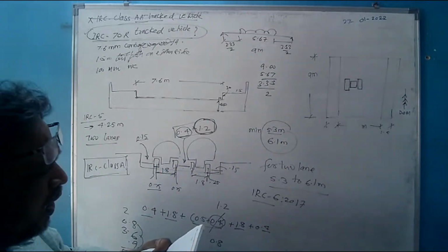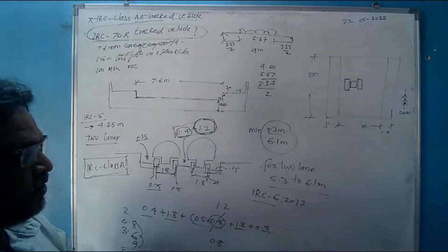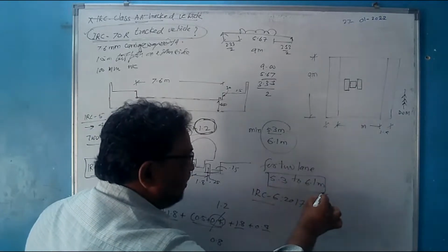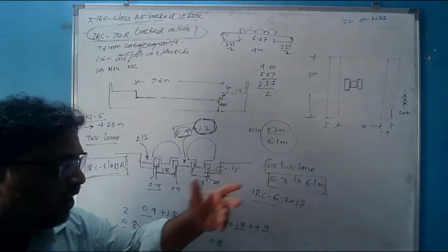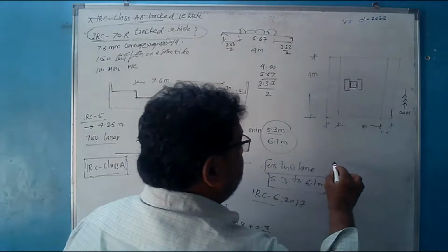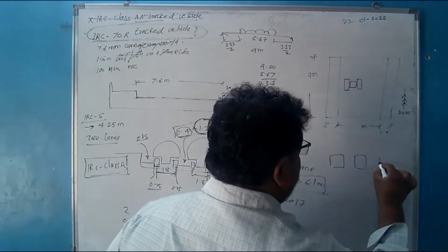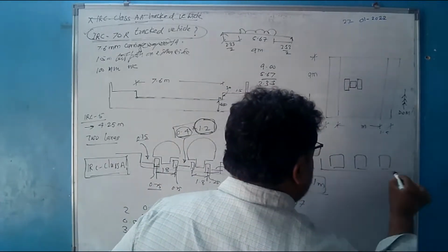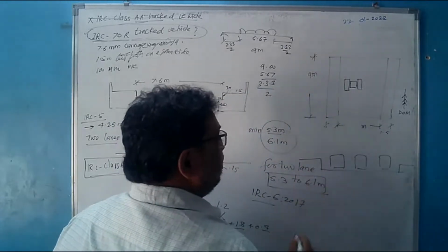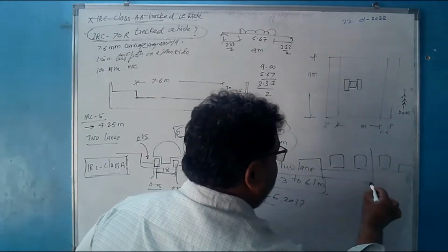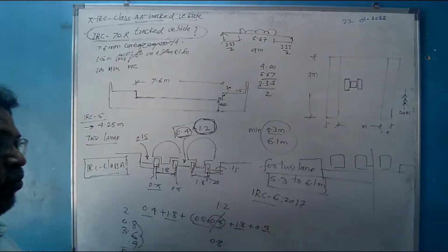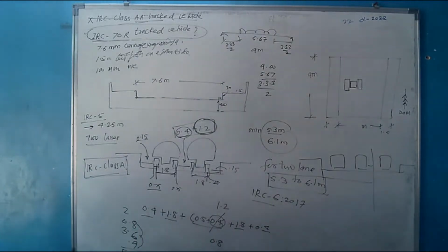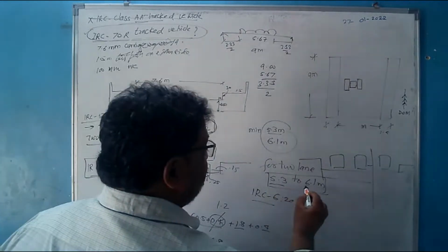तो अगर टू लेन, अगर if I want a bridge to be a two lane bridge तो मिनिमम इतना गैप रहना चाहिए. अगर इससे ज्यादा रखा तो I cannot directly call a three lane, क्योंकि थ्री लेन के लिए मुझे और एक व्हीकल पास होना चाहिए वहां से. तो उसके बाद मुझे और एक व्हीकल रखना पड़ेगा, वन व्हीकल, सेकंड व्हीकल, थर्ड व्हीकल. अगर तीन व्हीकल पास हो सकते हैं ब्रिज से, then only I can call this a three lane bridge. अगर मैंने इतना रखा विड्थ ऑफ ब्रिज तो it is 2.5, but 2.5 there is no sense in that. So that I will call as that we can provide only two lanes. So this is minimum 6.1, 5.3 से 6.1.